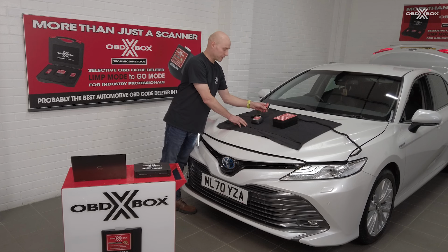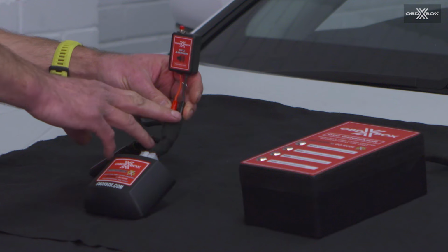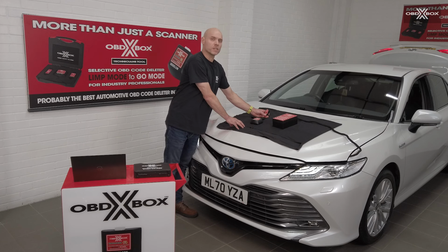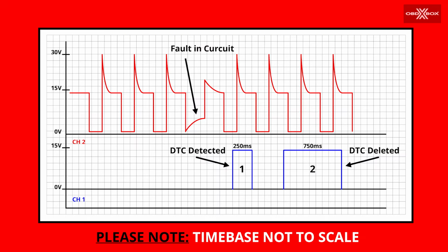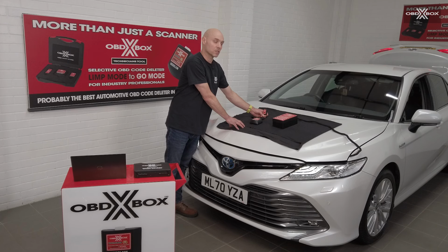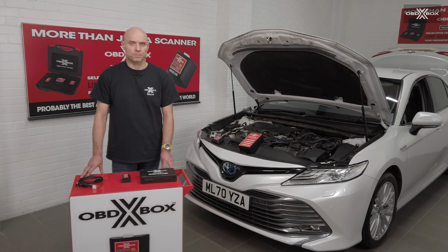In addition to using the bleeper, we can also connect an oscilloscope into these BNC connectors. If we're using the oscilloscope with the DTC alert function, we can use the square wave marker and see how it aligns with other signals that we may be sampling at the same time with the oscilloscope to see what occurred at the time that the fault occurred. I'd now like to show you how to program the Fix Assist module to help you with intermittent faults.